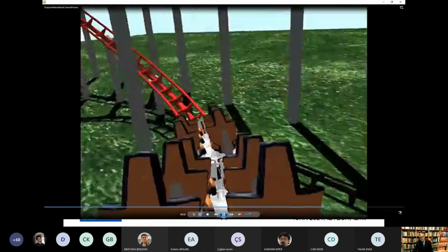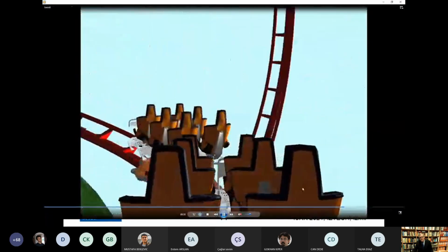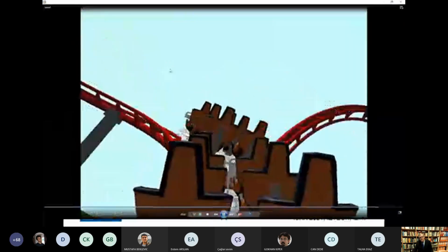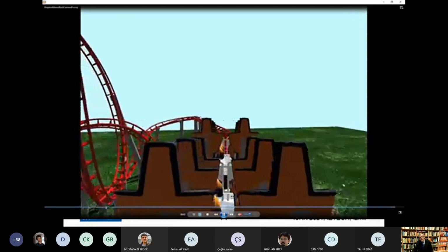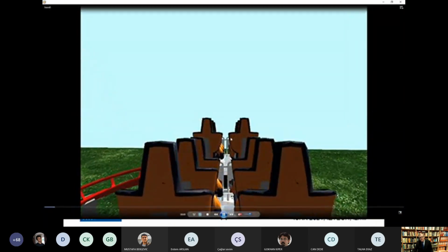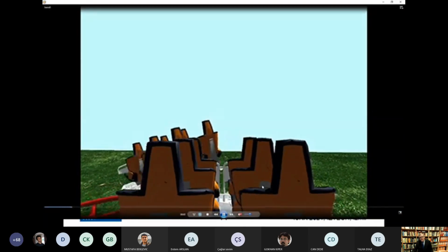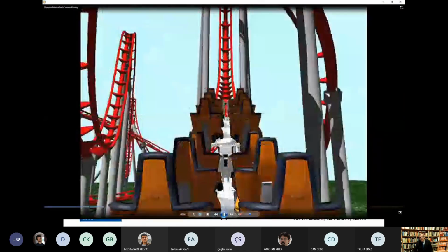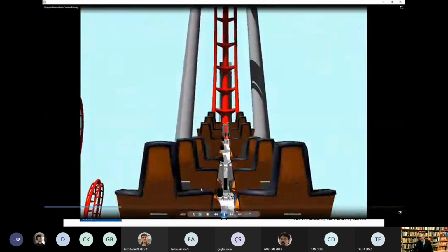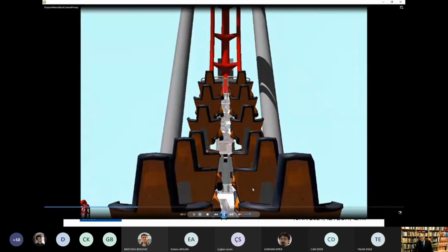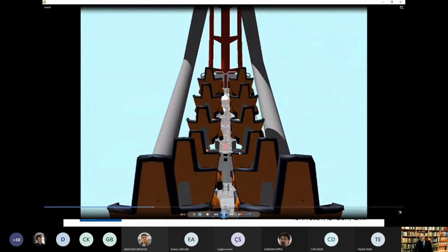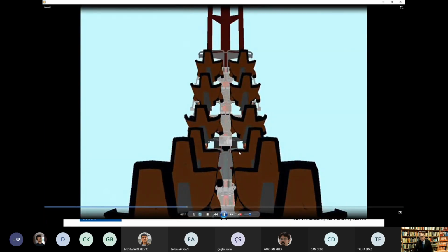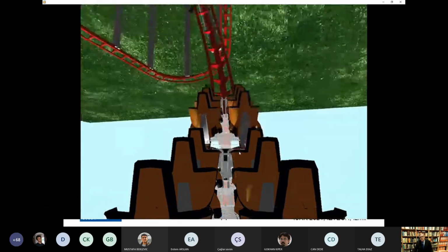And we use a complete dynamic simulation over the whole track to compute the accelerations at every seat. As you can see, the accelerations are not the same wherever you are, because maybe the front one will be in another situation, combining centrifugal forces, than the back one, and the velocity, of course, when you reach a point on a rail is not the same for the front and for the back seat. And so all of these are tracked, and then the task is to shape the geometry of this track so that